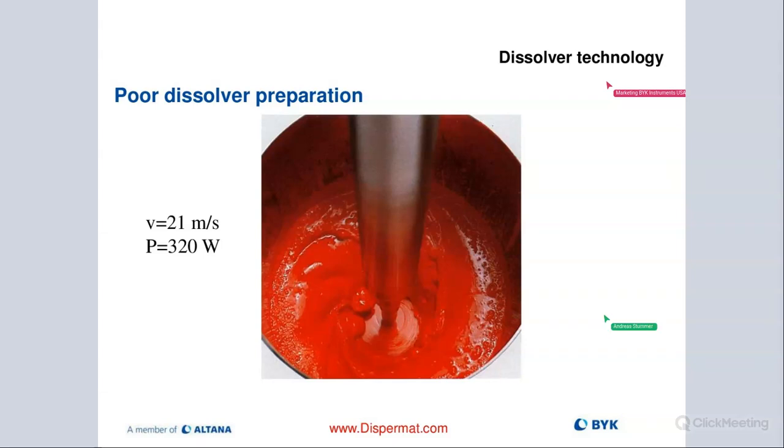This is where the donut is having a difficult time being formed because there's just not enough viscosity. Okay, so that would be an issue. You could try to increase the tip speed somewhat, but it would probably be better to look at the formulation and see if there is an adjustment that can be made to increase the viscosity somewhat, allowing us to put in more energy.